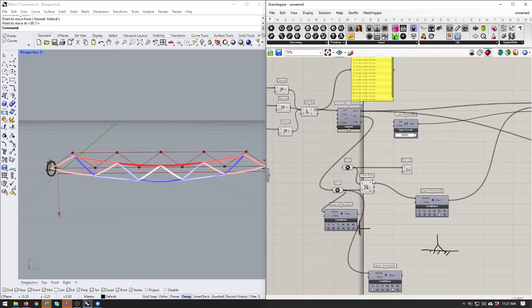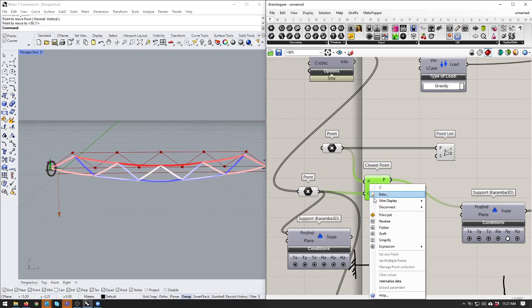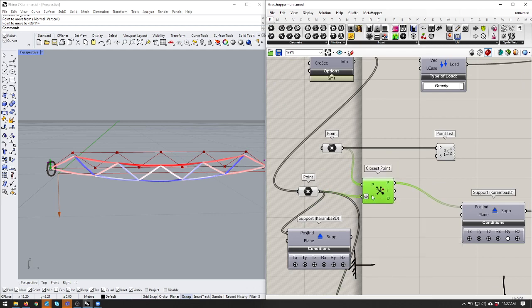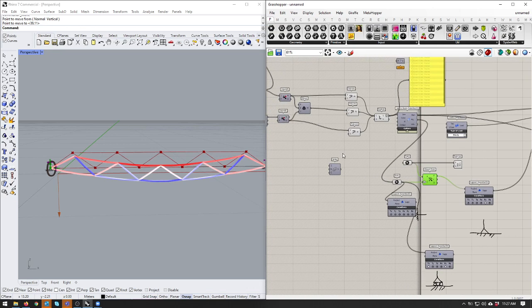The one reason why we want to flatten the system through here is because it is also going to be affecting our closest point. So if we've got any branches that are happening, branching before this closest point system, we probably want to get rid of them as well. So flattening that cloud will be useful in a moment.